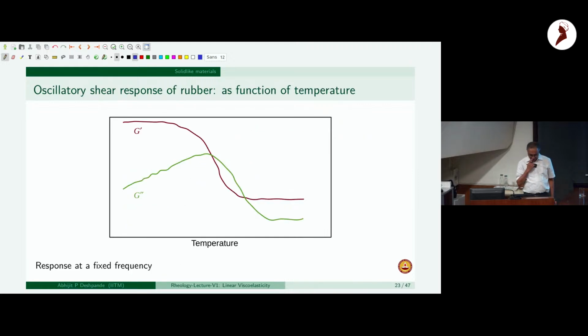And so if temperature is increased, you come to a rubbery phase, which is most materials like tire and all those things at room temperature are rubbery. But if we take them to, let's say, minus 80 degrees, then they would be glassy and it would shatter, right? Just like any brittle glass would. And this is basically response at a fixed frequency.